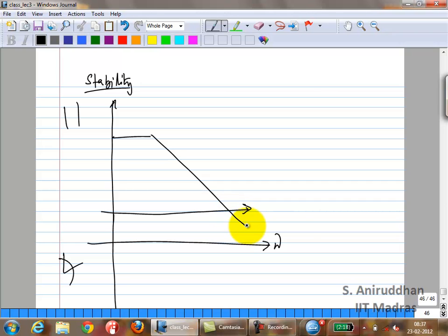Something like this. This is ideal, right? This is what you want, GM1 over C. You want a single pole, GM1 over C. With the parasitic capacitance, the DC gain did not change, correct? So let's say you go down this.